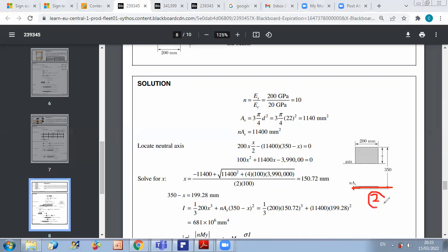But because this area is of negligible thickness, its inertia with respect to an axis passing by its centroid is 0. Because what will make the inertia is to have a distance from the axis. If all points are on the axis, no inertia about this axis.